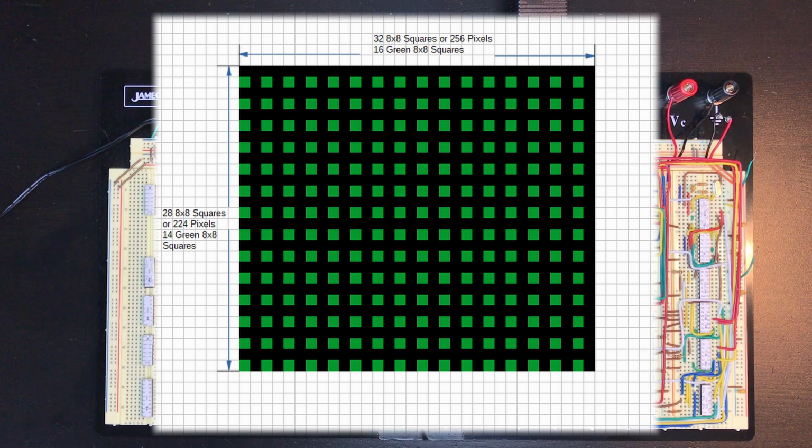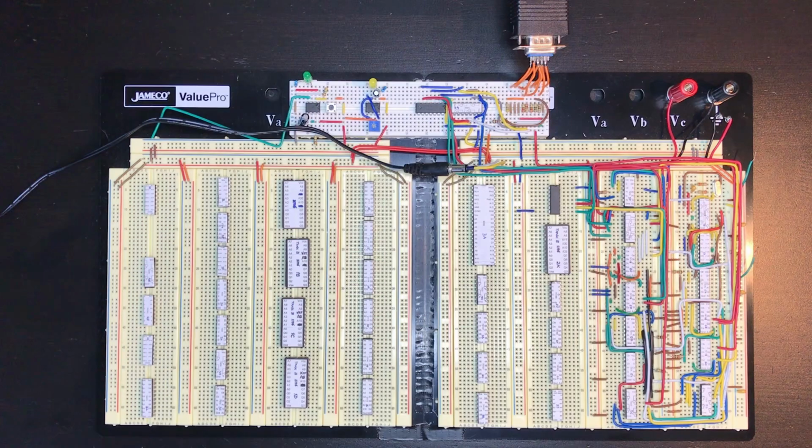One thing to note is that typically our tile graphics are going to be 8x8 size blocks, since memory chips love to hold 8-bit sizes of data. We'll see more about this going forward in the series, but there's definitely a nice order to the whole system of multiples of 8. So we'll be showing all of these red, green and blue signals at the same time, whenever we're not in our H blank or V blank timings.